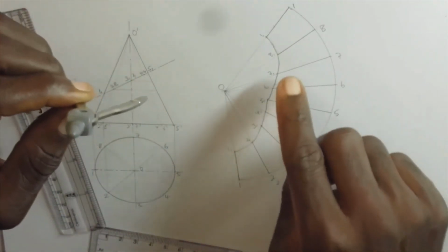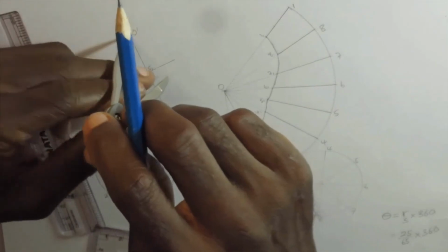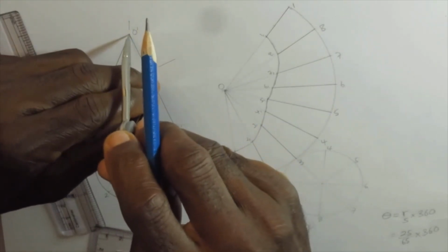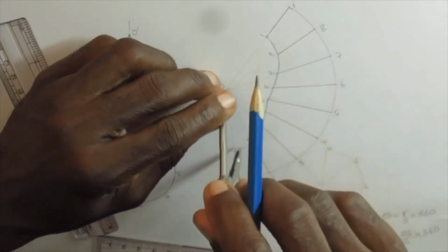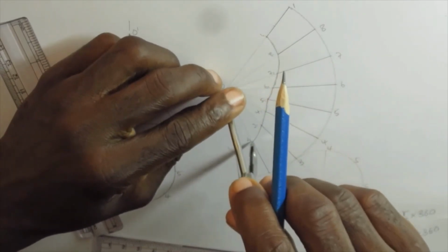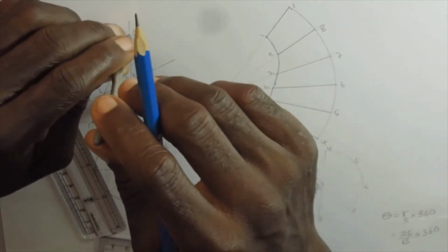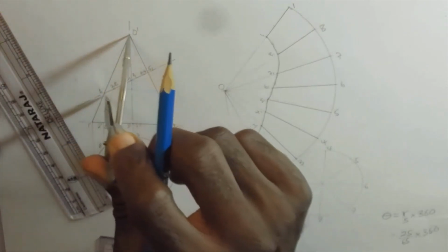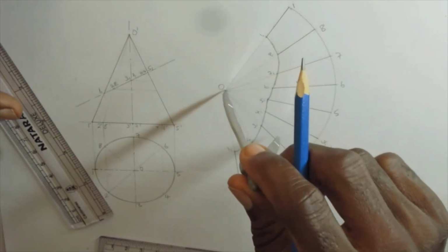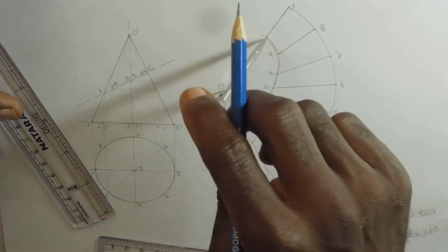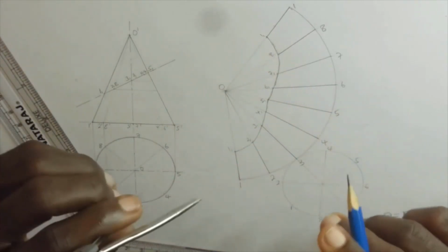All right. Then you have to label them. So we've labeled each of them. Then you go to the next one, which is 2 and 8. So from O, you mark 8 and then 2. Okay. Then you go to the next one, which is 1 subscript 1. Right. So that's because the one lies on the slanted edge, the outer one, which is the true length. We can use that. We don't have to project to the other side. So just pick that distance, then you mark here and also mark at that point. So we label them 1 subscript 1, 1 subscript 1.